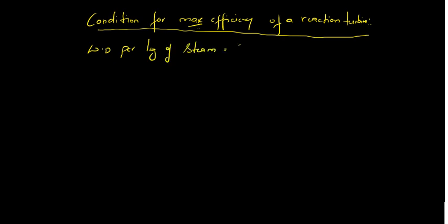equals VW1 plus VW2 multiplied by U, right? Per kg. That is the reason I am not writing the value of m here, right? Now, if I correlate it with the velocity diagram, I'll tell you how to draw the velocity diagram for this reaction turbine in the next sessions, right?